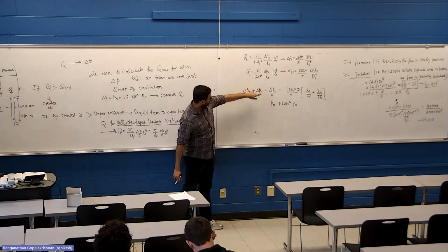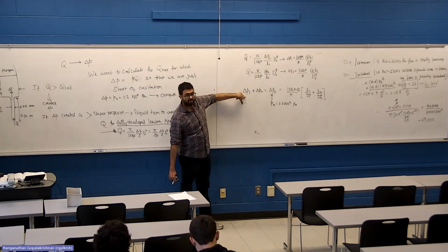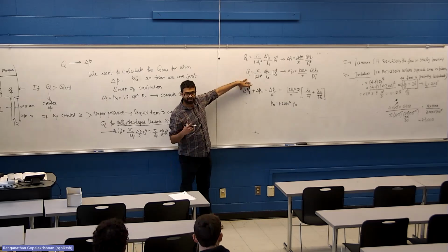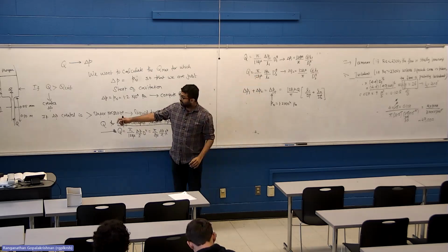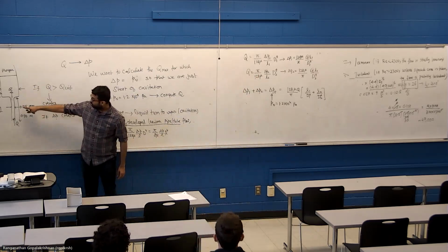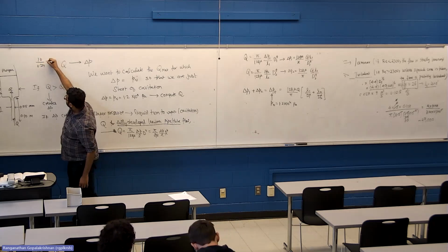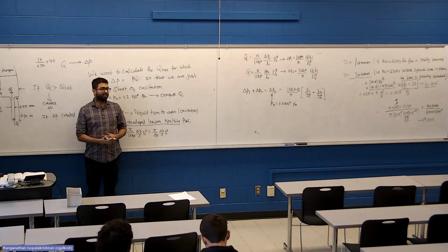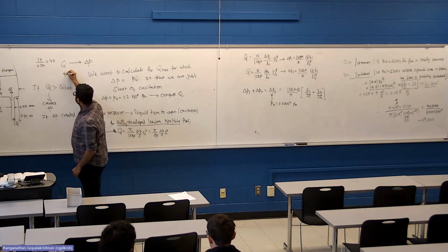We have set up the equation for the total pressure drop in terms of the pressure drop in each section. Without doing any calculation, you could say the pressure drop in the needle will be much more significant than in the syringe, because they have a diameter ratio of nearly 10 divided by 0.25. That's 40 times. If the diameters differ by 40 times, how much will the pressure drop differ by? 40 to the 4th power.